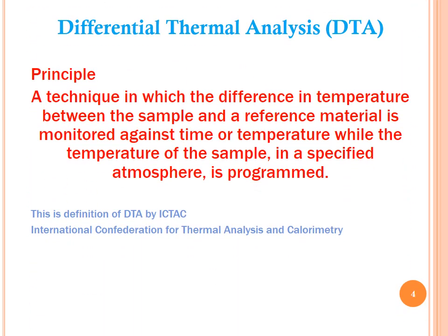So differential thermal analysis has a specific definition given by ICTAC, the International Confederation for Thermal Analysis and Calorimetry: a technique in which the difference in temperature between the sample and the reference material is monitored against time and temperature, while the temperature of the sample in a specific atmosphere is programmed.